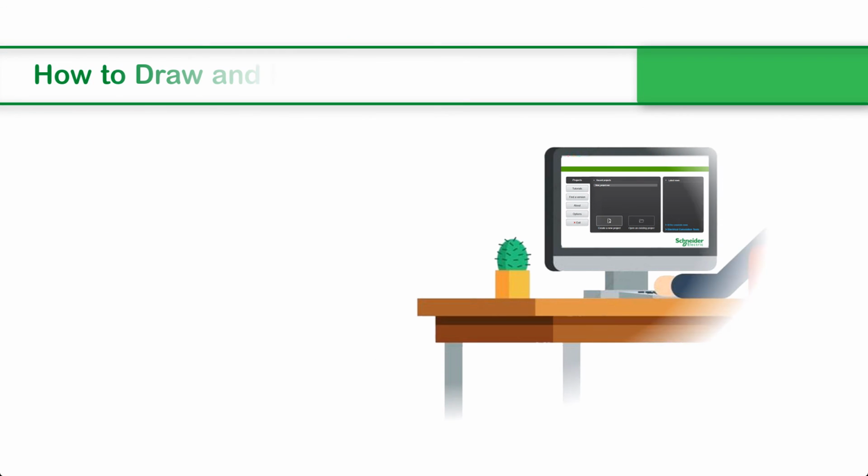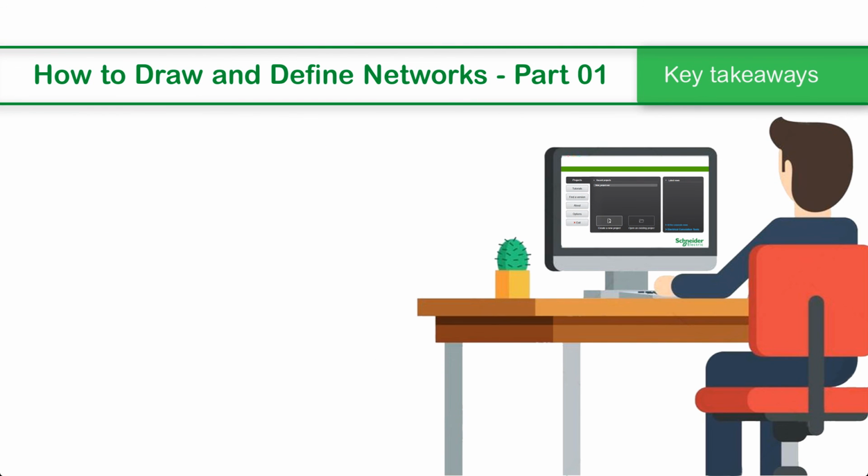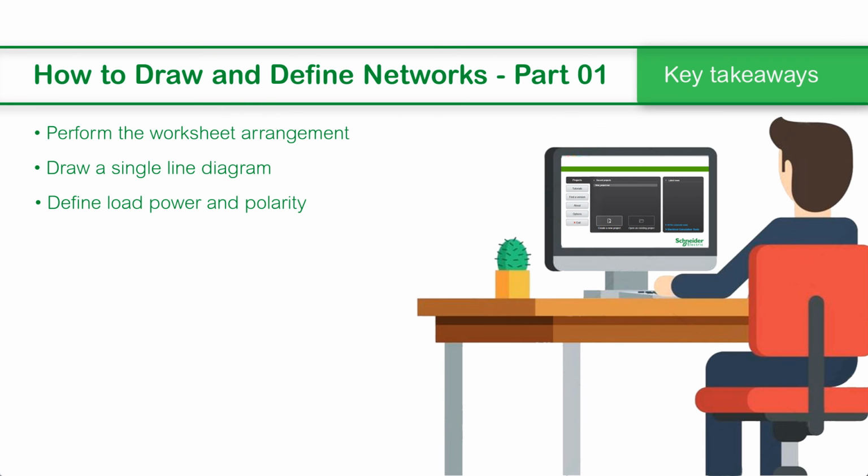This concludes the video on how to draw and define networks in EcoStruxure Power Design EcoDial. In this video, we saw how to perform the worksheet arrangement, draw a single line diagram, define load power and polarity, and define system earthing arrangement.